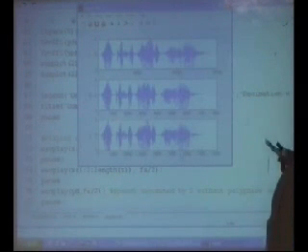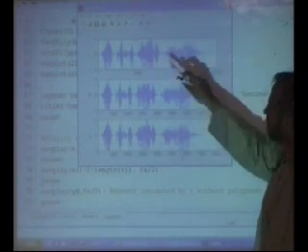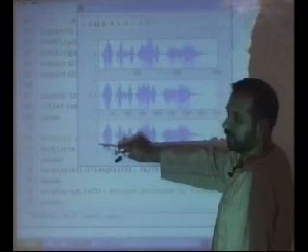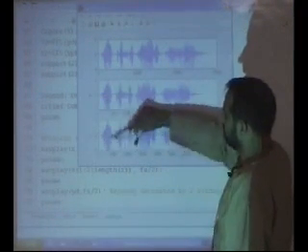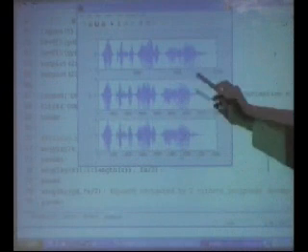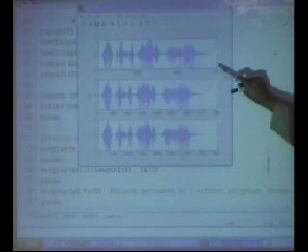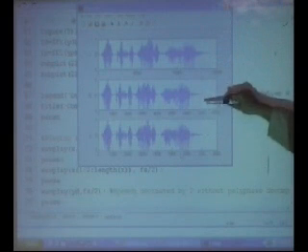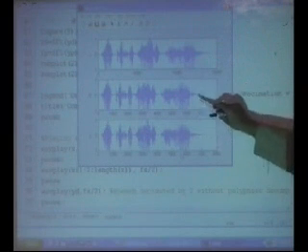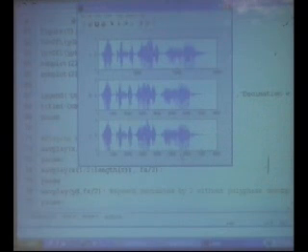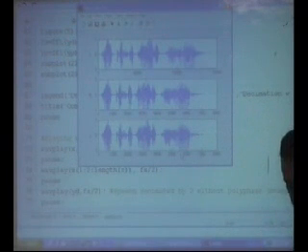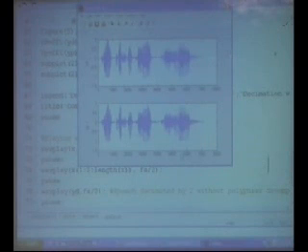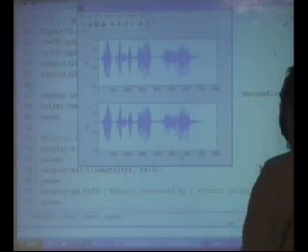You do the same with this input signal, this X. You give the first sample to this one, second to this one. So out of so many samples, 14000, you have 7000 to this one and 7000 to the other. I pass through P0 and pass through P1, and then add them together to get the output. Here I am showing the same output.